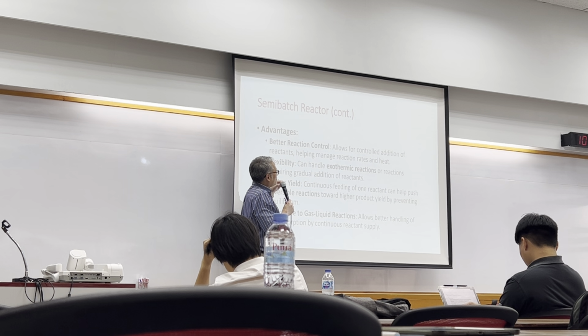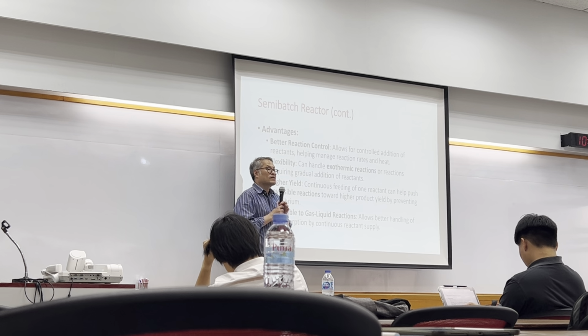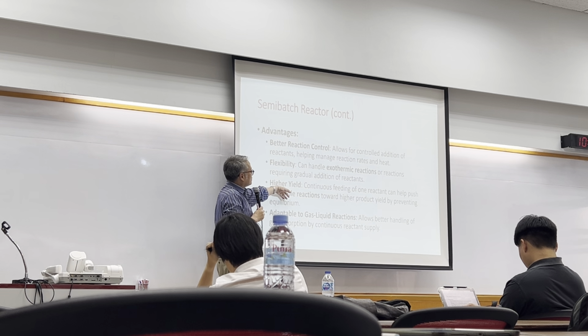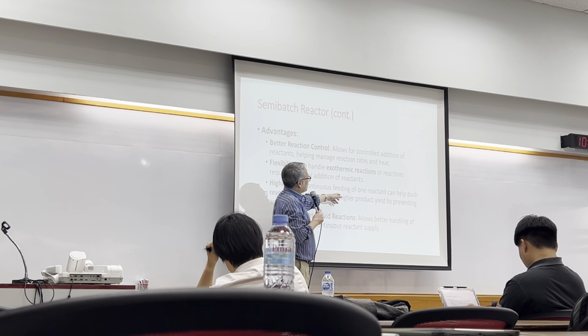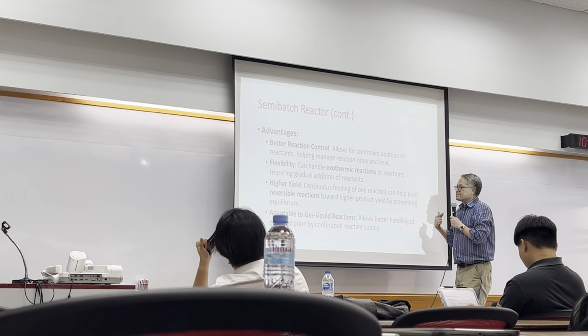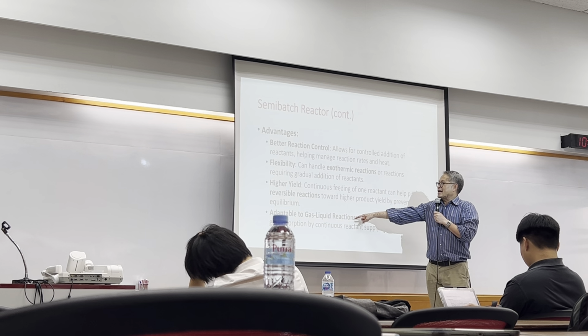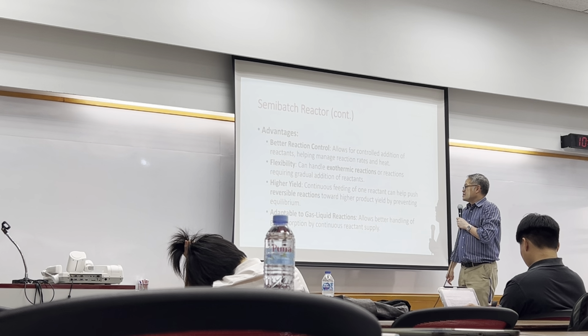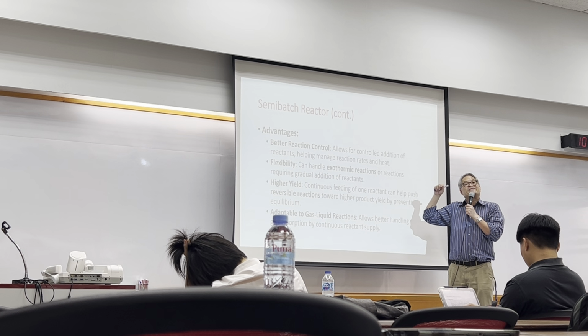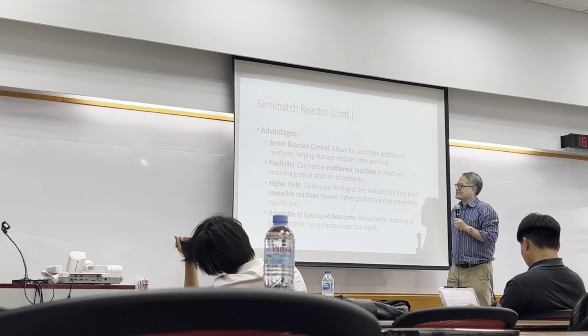If we control the addition of the reactants, we can control the product distribution. Higher yield: continuous feeding of one reactant can help push the equilibrium to the product side. And adaptable to gas-liquid reactions. You have liquid inside the tank, and you keep feeding the gas.